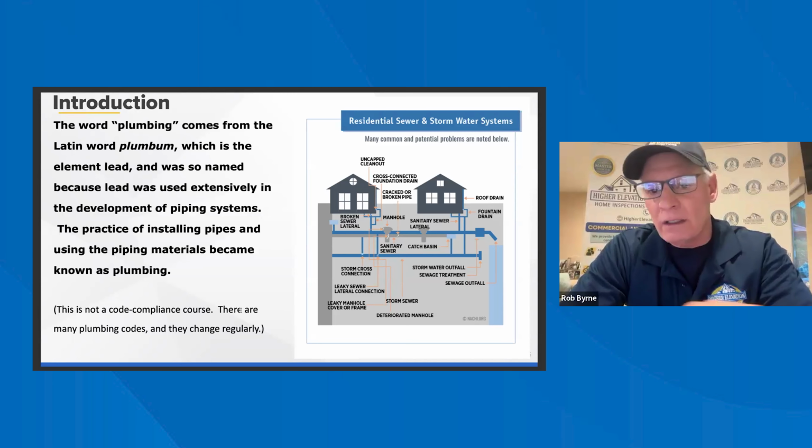Now, we run a lot of water. I want to see water in here. I want to put a couple inches of water anyway in the bathtub. If it is a shower, we do not plug the stopper and do a water test of the shower pan. It is not required for InterNACHI standards of practice. In fact, it's discouraged because a lot of times if it does leak, you will damage the house. Then you are responsible. So do not do a water test on a shower. Just run it as normal, which is open up the faucet.